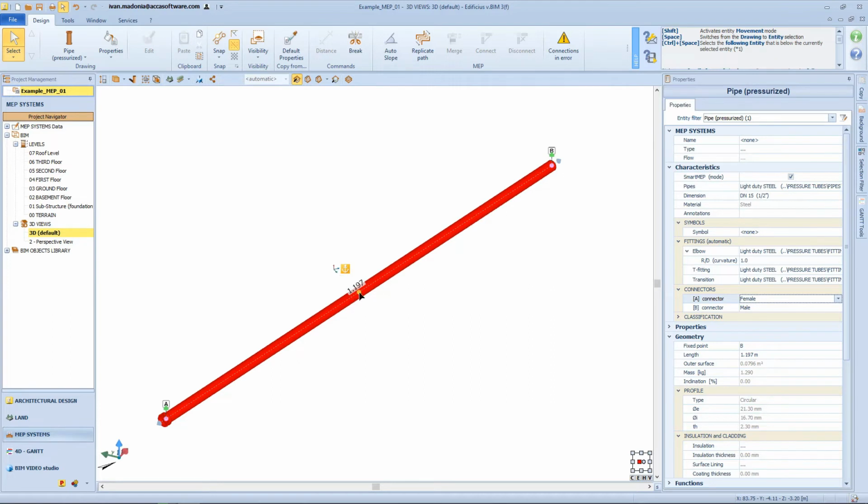By clicking on the icon representing the triad of axes, shown next to the anchor, the object grip for rigid rotations and displacements of the pipe is activated. By default, the object grip is centered in the orange circle corresponding to the anchor positioning point and is arranged in the plane perpendicular to the pipe axis.